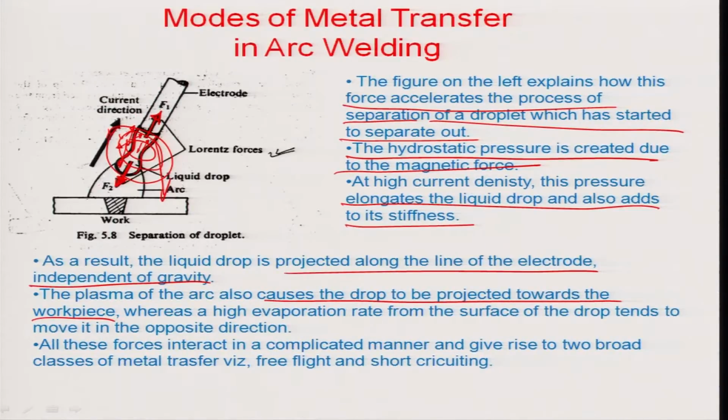Obviously, there is going to be a formation between the melt drop and the iron. So, there are many current paths which are created between the two, and there is a plasma in this particular zone. So, it is a kind of hydrodynamically focusing arrangement that the plasma offers, and this droplet, which has been separated because of Lorentz forces and a combination of the surface tension and the gravity forces, is now coming into the path of the plasma and being hydrodynamically focused onto the workpiece.